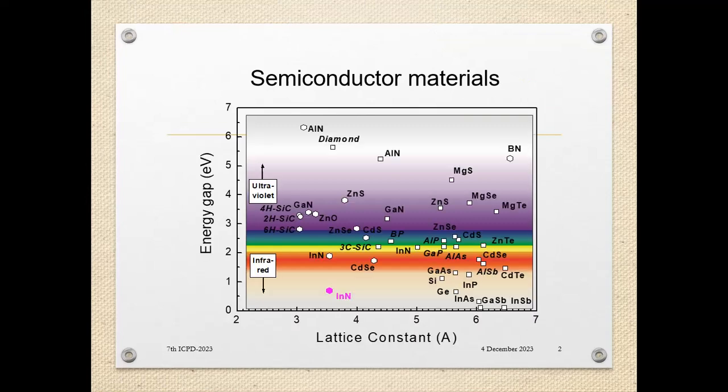So we try to develop transparent devices using zinc oxide and silicon germanium nanocrystalline materials developed on ITO glass substrates, and the P contact is made by the organic material PTAA. Here you can see the zinc oxide in the ultraviolet region, and silicon germanium, though it is in the infrared region, with nanocrystalline materials interfaced with silicon dioxide can become transparent, with higher band gaps.